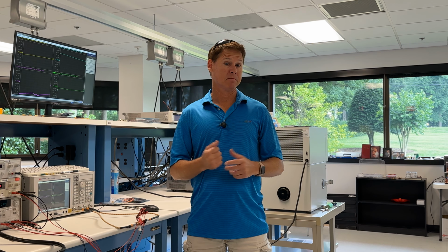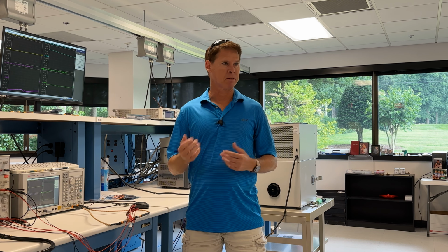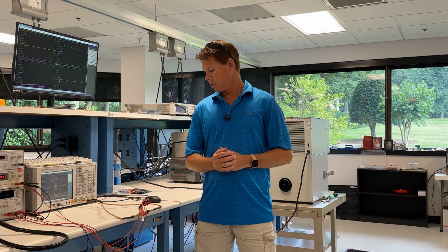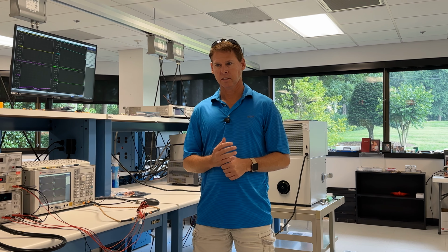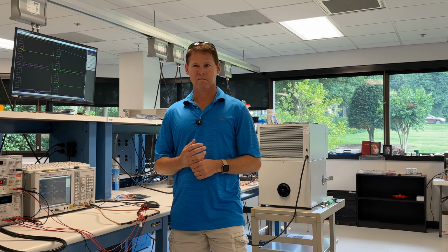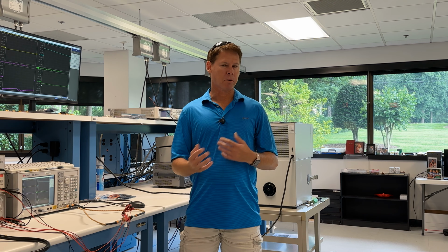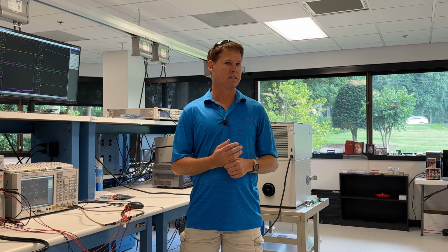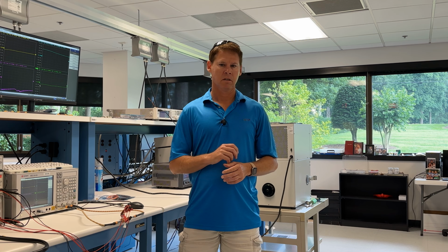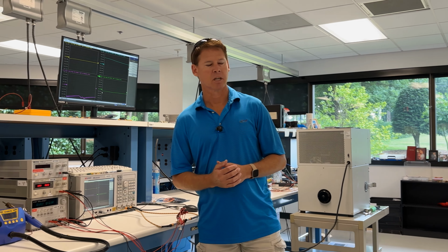Ideally, we would put a little pigtail on the board, do another port extension, and then you would have freedom to optimize all three. But in this case, this is more of a simple interstage. Other parts, we may have an inductor feed that we could try to optimize. This is purely a trace, as low inductance as possible for these high frequencies. So it's probably not necessary, but it could certainly help to optimize.